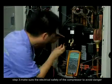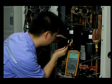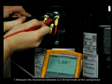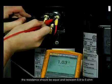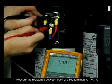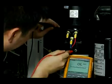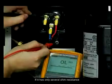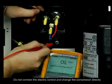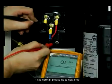Step 3. Make sure of the electric safety of the compressor to avoid danger. 1. Measure the resistance between the U, V, W terminals of the compressor. The resistance should be between 0.9 and 5 ohm. Measure the resistance between each of the 3 terminals, U, V, W, and the ground to make sure it is in the mega ohm range. If it has only several ohms of resistance, that means the compressor has been short circuited and damaged. Do not connect the electrical control or change the compressor directly. If it is normal, please go to the next step.